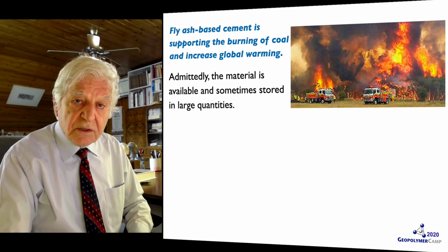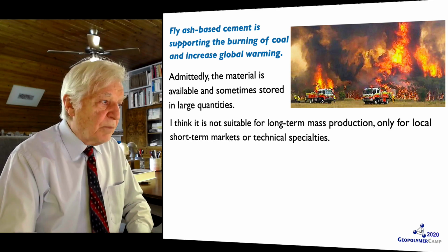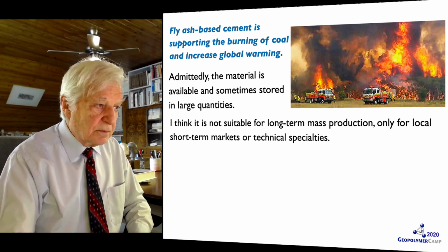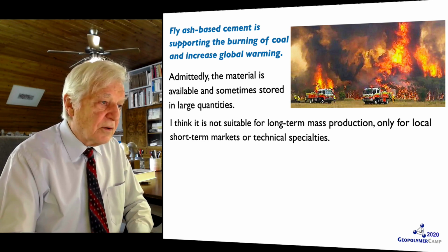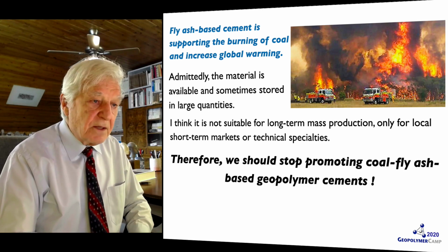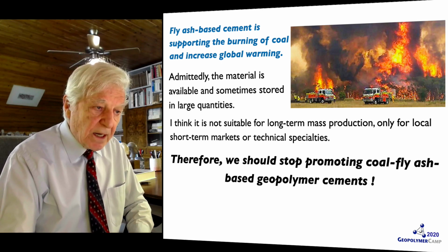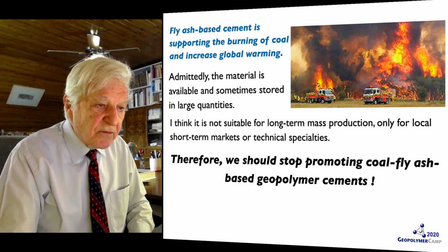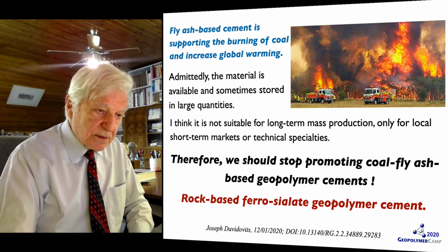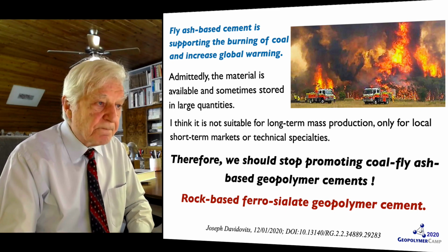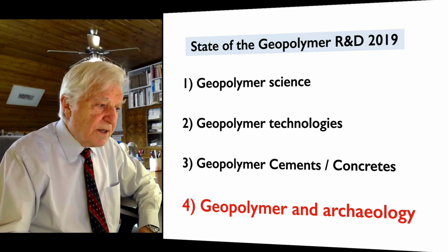Admittedly, the material is available and sometimes stored in large quantities, so it can be used, but I think it is not suitable for long-term mass production, only for local short-term markets or technical specialties. Therefore, we should stop promoting coal fly ash-based geopolymer cement, and I strongly recommend to replace fly ash with rock-based ferro-sialate geopolymer cement technology. After this strong statement,